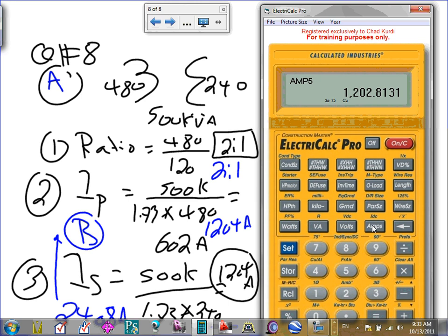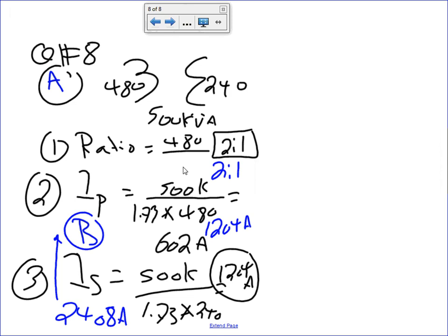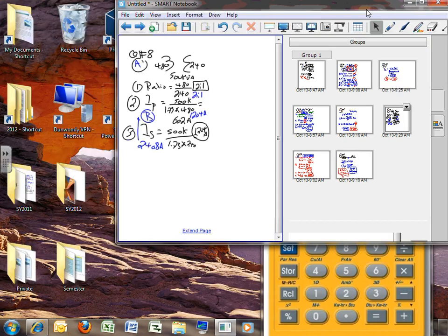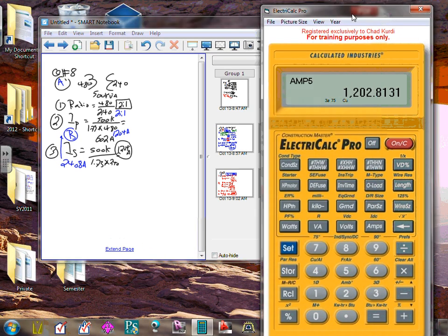Okay, any question guys? Chris, my friend? Turns ratio on question A where you have 480 over 120. Yeah, so 2 to 1, not 1 to 2. 120 goes into 480 4 times. Oh, I'm sorry. This should be 240 here. This should be 240. All right. You're absolutely right. Thank you. This should be 240. It's right on the quiz, right? 240. No, I didn't know if A and B were the same. No, they're completely the same, identical.